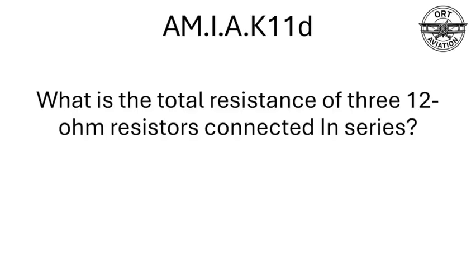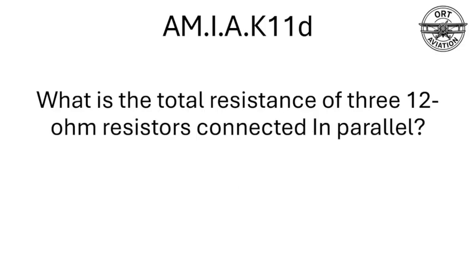What is the total resistance of three 12-ohm resistors connected in series? 36 ohms. What is the total resistance of three 12-ohm resistors connected in parallel? 4 ohms.